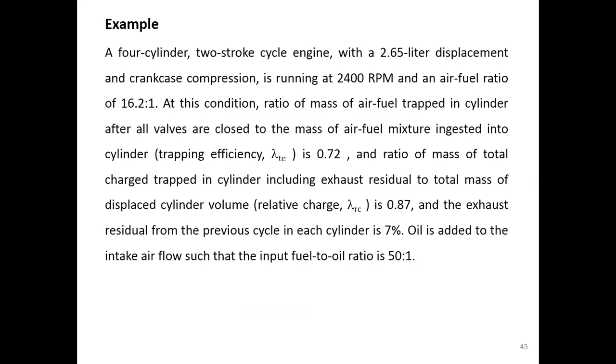In fact, it's supposed to be the same mass, but it is not. Why? Because along the way as we draw the mass into the cylinder, the intake valve is open and the exhaust valve is also open.